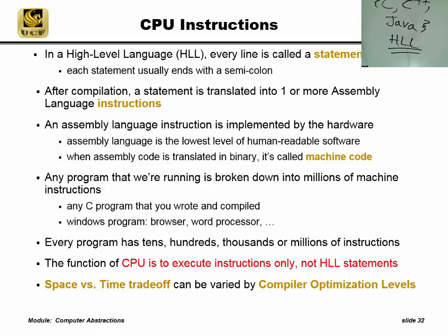So that's the job of the compiler to make the translation to assembly and assembler to make the translation to binary or machine code. So the interesting thing as engineers, people usually hire us to perform trade-offs, is there's what I call a space versus time trade-off. Well, a lot of authors call that. It's a very fundamental concept. We can use more instructions and have maybe a different time trade-off, which means how long it takes to execute. So this is a number of physical resources, including chip area and even energy, versus execution time.